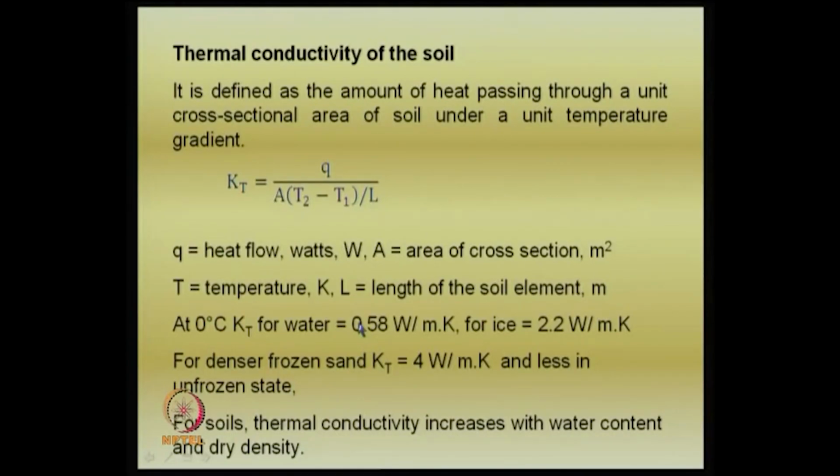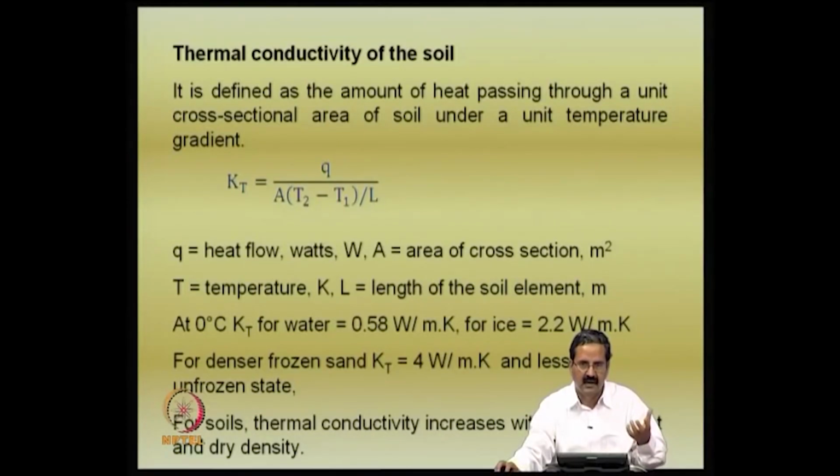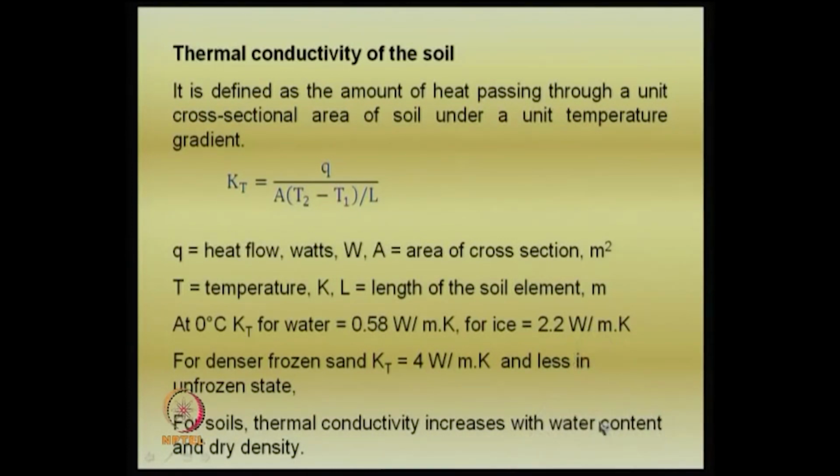Once you heat the soil, the water content is removed, and then the stiffness increases, the strength increases, and there are so many properties that you get. For soils, thermal conductivity increases with water content and dry density. This is an important factor that we should understand: the higher the water content, the higher the thermal conductivity. Because of the presence of water there is an increase in thermal conductivity, and also with dry density, since the particles come closer to each other when the soil is dense, you have a better thermal conductivity.